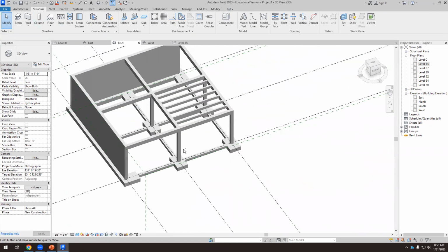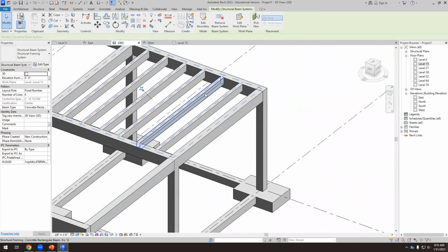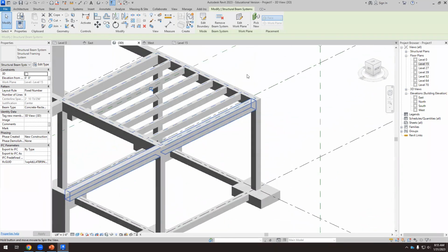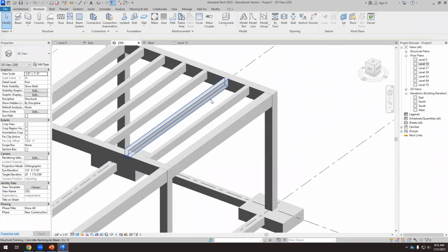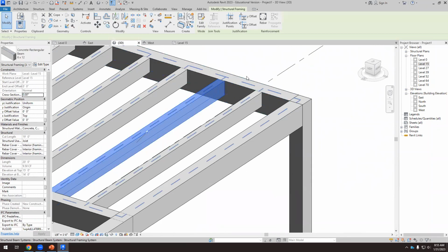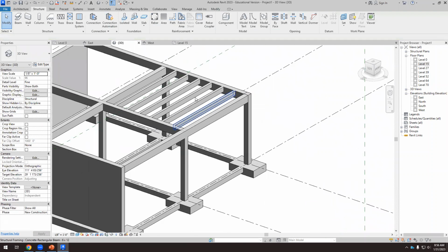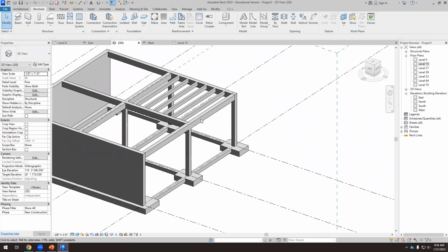Okay, so this is the first option. We can have a beam system made of concrete beams, but the beams of the beam system should be smaller in size than the main beam of the system. Again, we have to calculate this, but as a rule of thumb, this is a good criterion.